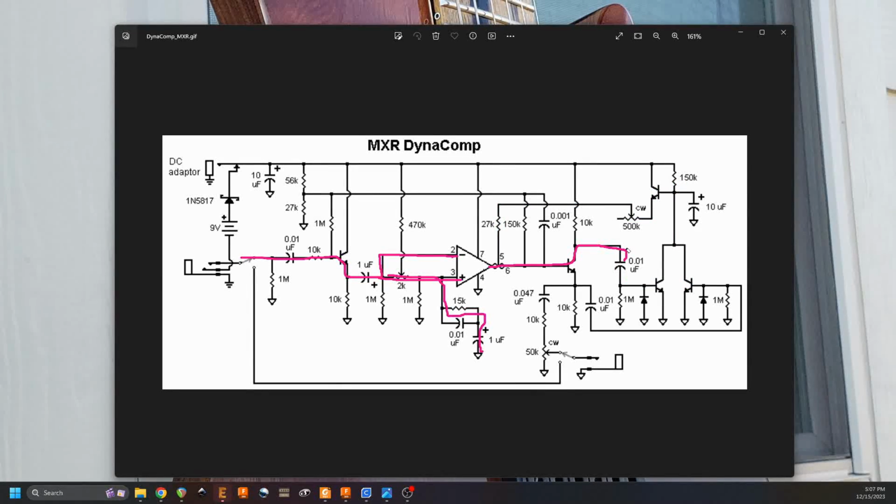It's one of those things where the operational transconductance amplifier can be a very mysterious component, but even though I have glossed over a ton of information, the important thing to remember is that it's going to amplify the difference between our two terminals and turn it into an output current because it's a current amplifier, and that if we put a current in on the pin that corresponds to these two little circles here, I don't even know what they're called, that acts as a control current that will actually reduce the overall amplification of the stage. And that's what our envelope detector is doing.